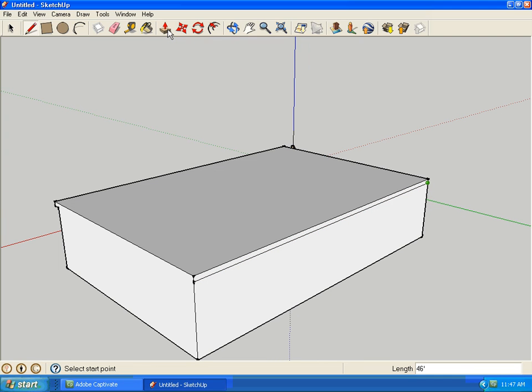As before, click on the push-pull icon in the toolbox and draw the cursor down to within the newly drawn eave. Click twice. Again, SketchUp has remembered a previous command and automatically extrudes the eave 12 inches.